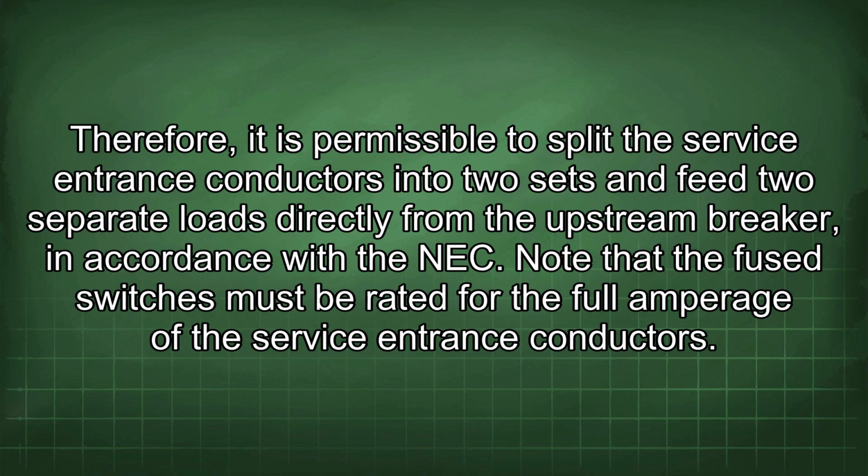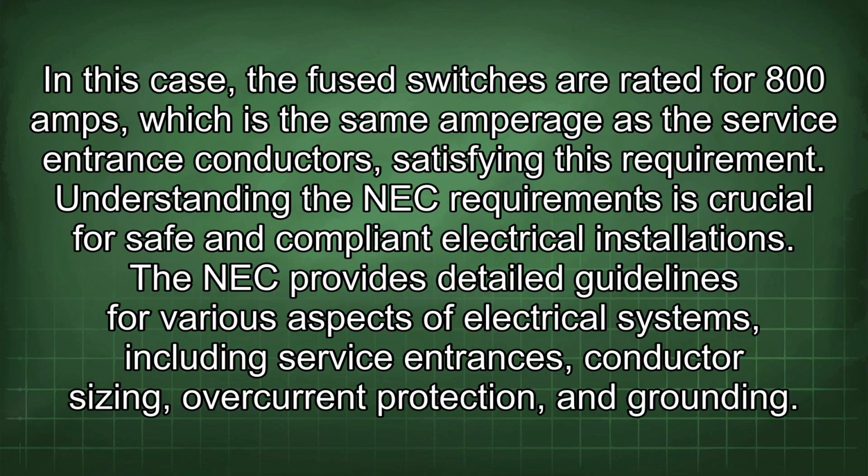Note that the fuse switches must be rated for the full amperage of the service entrance conductors. In this case, the fuse switches are rated for 800 amps, which is the same amperage as the service entrance conductors, satisfying this requirement. Understanding the NEC requirements is crucial for safe and compliant electrical installations.